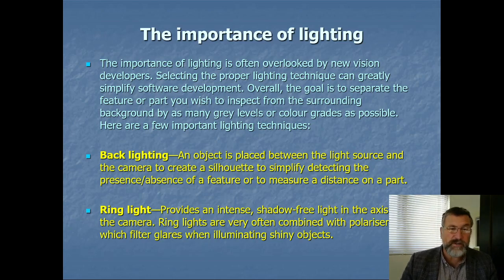Now, it's a similar kind of idea with removing glare using polarization. So what we've got there is, say, cellophane wrapping on an object. When the light's reflected off that, reflection from a non-conductor tends to polarize the light. So the light being reflected will have a certain polarization. By putting a polarizing filter on the camera, you can adjust it so as to minimize that particular reflected light. So then you stand a better chance of reading the barcode underneath. There are other ways of doing it, but that's a couple of examples there, really.